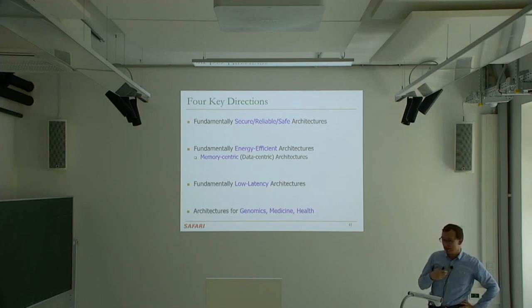Okay, to be fair, we didn't really design the embedded device yet because we're still working on the algorithms and the FPGA. But if you look at the FPGA itself, we report a lot of numbers, and pretty much all of the memory is utilized in the FPGA. Is that what you were asking? I would like to know what portion, in percent, of the energy is memory consumption. In terms of energy, most of the energy is consumed by memory, around 90%. If you include all of the on-chip memory, it's more than 90%. Computation is very little, and computation is relatively simple here.